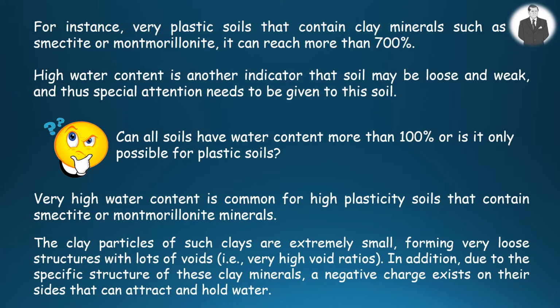The clay particles of such clays are extremely small, forming a very loose structure with lots of voids. Additionally, owing to the specific structure of these clay minerals, a negative charge exists on their sides that can attract and hold water.